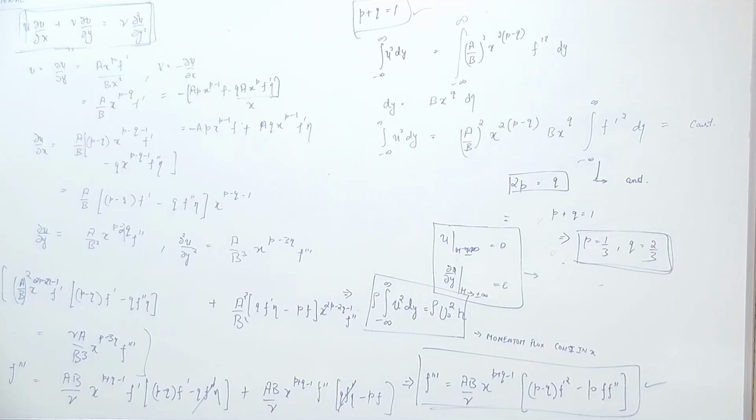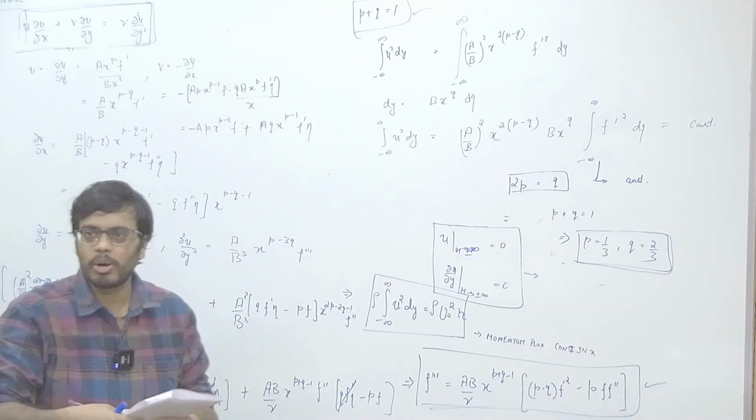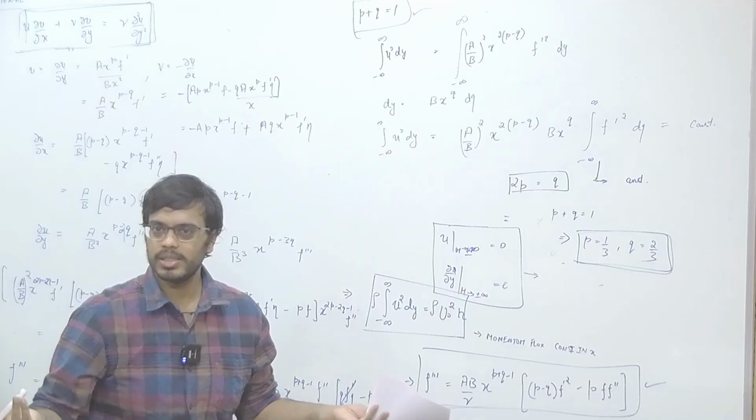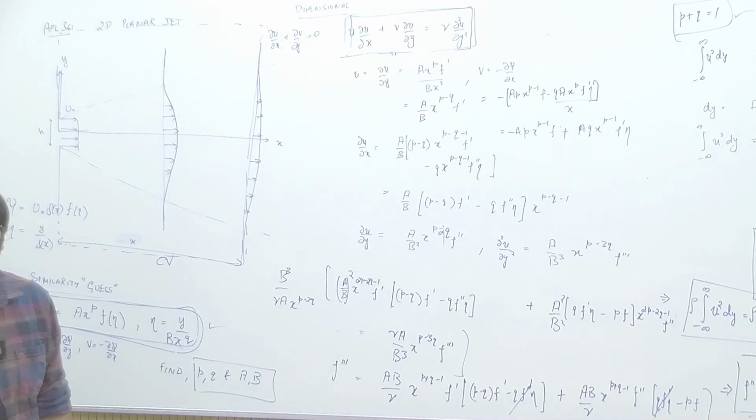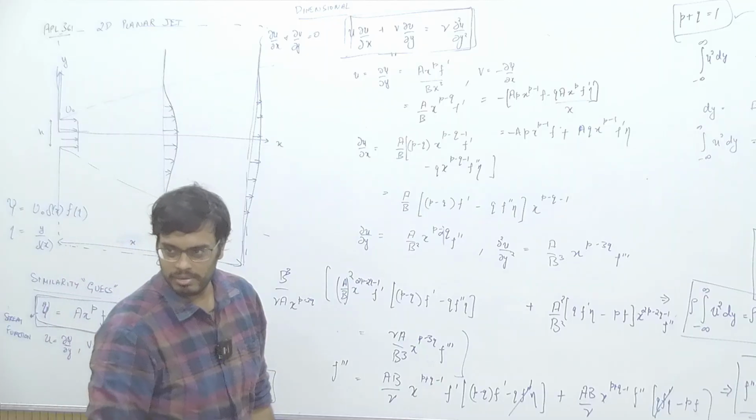If du infinity dx is less than 0, then what about dp dx? dp dx is greater than 0, it is an adverse pressure gradient, and you can intuitively think about it, right, that the flow is slowing down. When is the flow going to slow down? When the pressure gradient is adverse. Here the intuition about Bernoulli's equation is perfectly valid, because here we are deducing things from the inviscid zone.